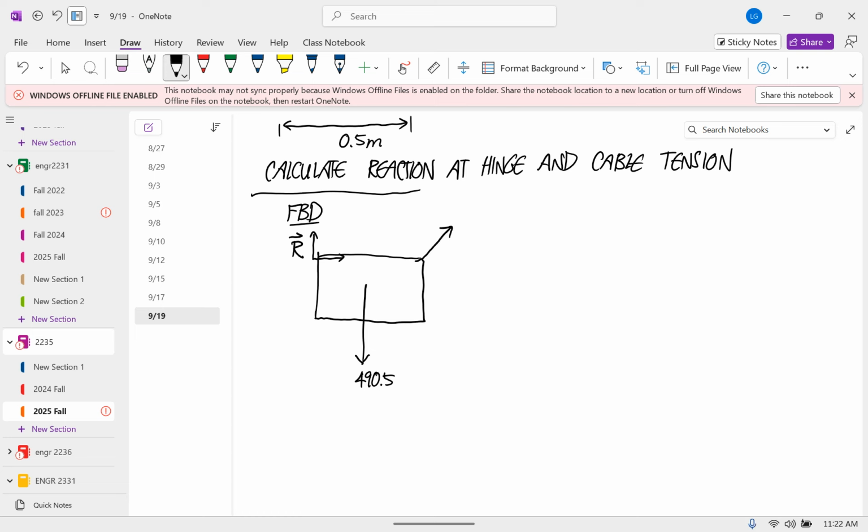Why is R not a moment since it can rotate? Because that's the thing that we're slowly going to try to get out of. Don't think about the motion that's allowed, think about the motion that's eliminated. So it's a hinge joint, it allows the rotation, and so that means there's no moment. It doesn't allow translation, and so those forces are applied. Okay, thank you.